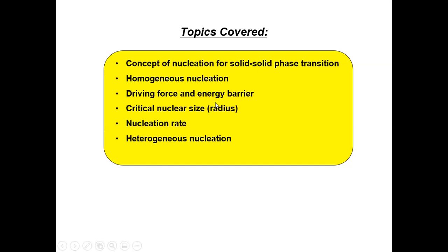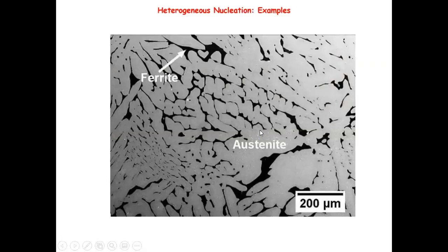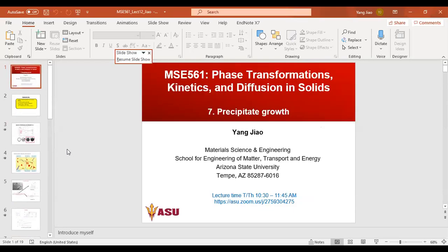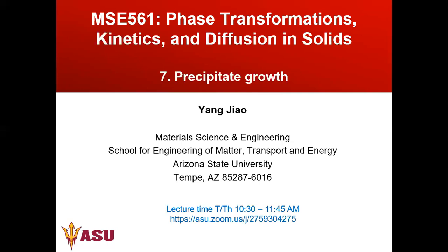Again, we went through these concepts of nucleation in solid-solid phase transformation. We talked about the homogeneous case and the heterogeneous case. The key idea we get is that heterogeneous nucleation is much more frequent in these solid-solid transformation mechanisms, and we'll see an immediate consequence of this. So that's about nucleation. I know I went through this fairly quickly because there's not too much new concept added. We're applying concepts we already introduced to the case of solid transformation. Now let's keep on with our processes.